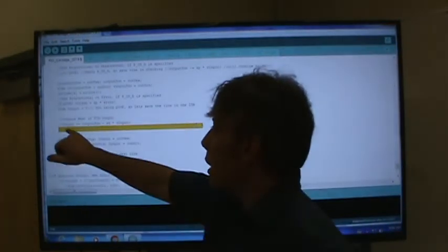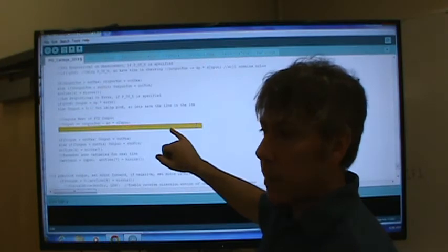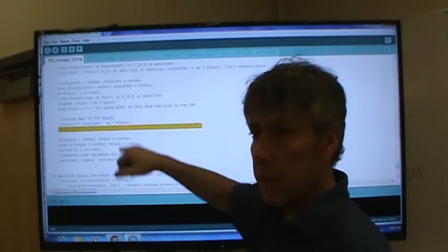It turned out that the conditions were fairly long, and if I could get rid of some of the conditional decisions, I could save a few clock cycles. But most of the work was in calculating the output. So for example, I put all of the PID calculation to calculate output from error on one line. And that took the longest time. That took about 4 times what anything else took.